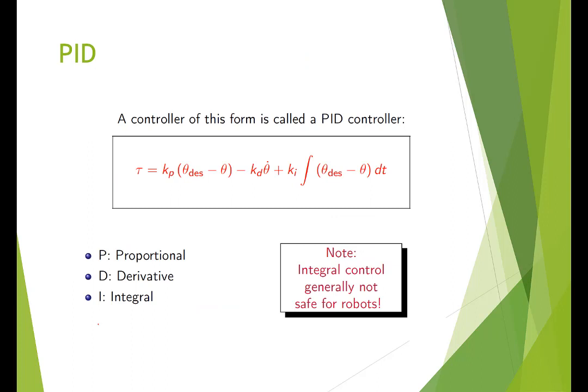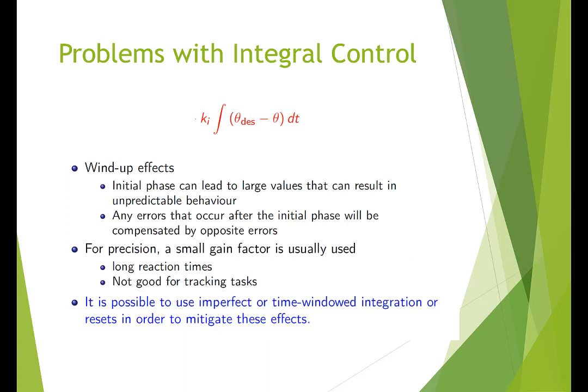Again, this is what we call the PID controller. Three terms: proportional, which acts like a spring; second term, derivative, acts like a damper; third term, integral term. One thing that we have to notice: a spring and damper we could visualize how it behaves, but what about the integral term? The integral term can cause some problems. We usually try to avoid it as much as possible. If that steady state error that we had was small, we can even forget about it.